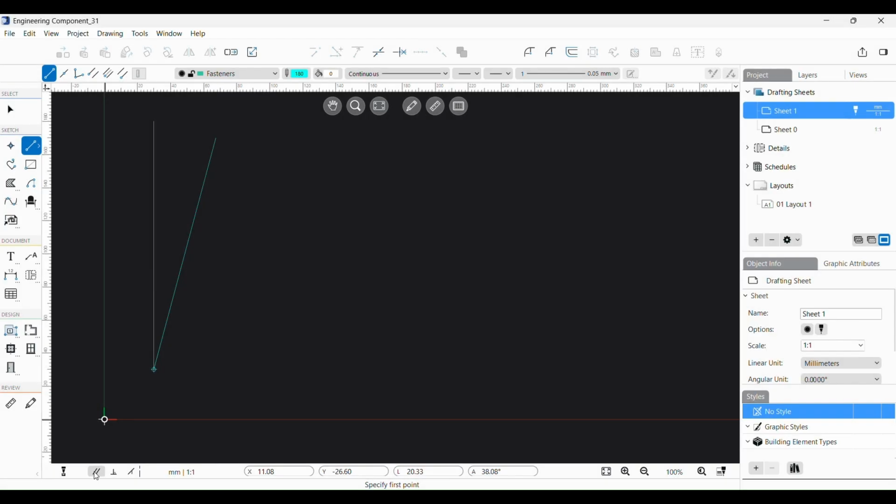Constrain parallel, P, and right angle, R. These conditions can be activated anytime, with any tool or editing function, and will affect the direction of the current movement. To activate the right angle or parallel condition, after the first click of the current operation you are performing, click the button corresponding to the desired condition or press its keyboard equivalent, P or R. Click the reference object, like the line you want to draw parallel or perpendicular to. The mouse cursor changes to a pointing hand when on a valid object. To cancel a condition, press the Escape key on the keyboard.